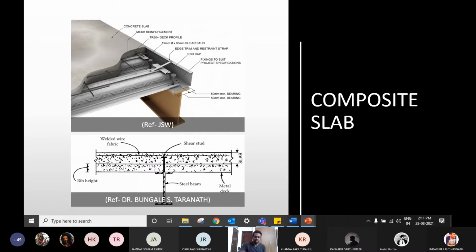Now the welding kind of spoils that local area, right? If it's at the edge, suppose this particular stud is somewhere here at the edge of the flange, when this structure is subjected to bending, it doesn't have enough edge distance. It's going to easily get knocked off. That is one of the reasons we need to have minimum bearing. Now you guys remember the importance of edge distance in your connection design, right?